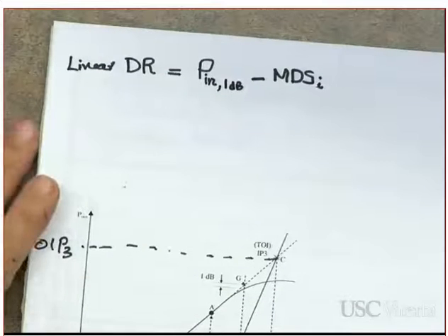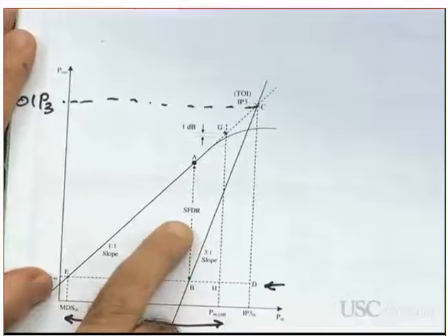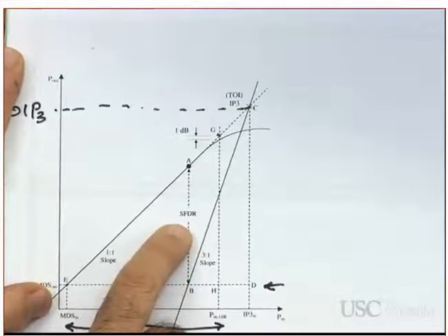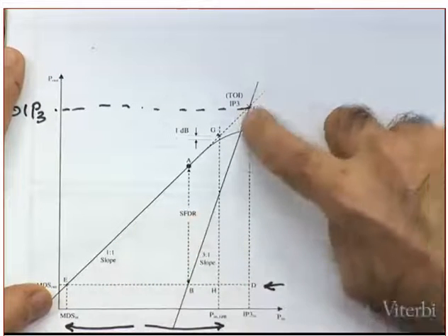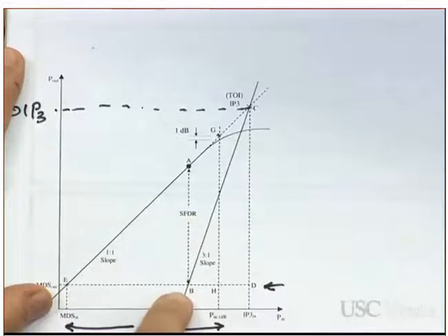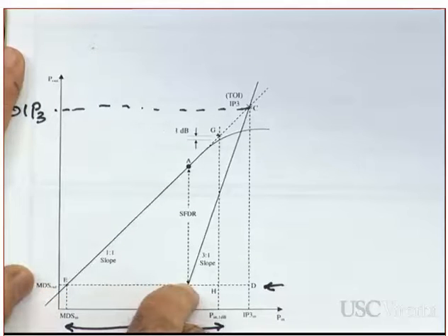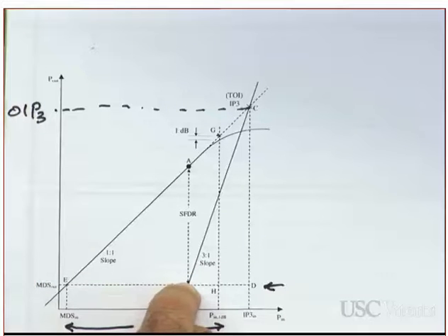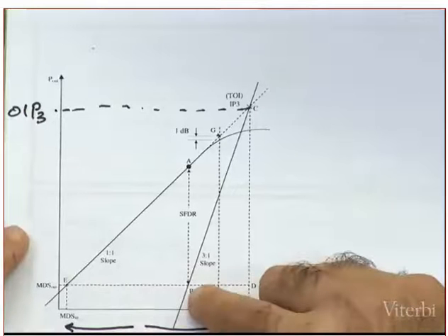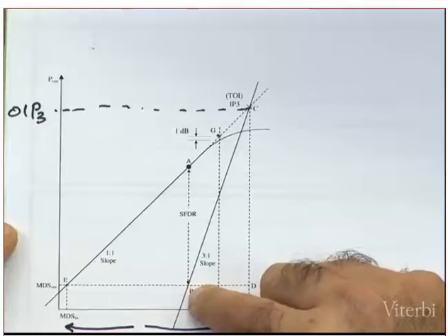Okay. Now, what is the spurious-free dynamic range? Let's understand the spurious-free dynamic range. It is when the third order intermodulation component power is the same as the MDS, or if the MDS is not given, the same as the noise floor.